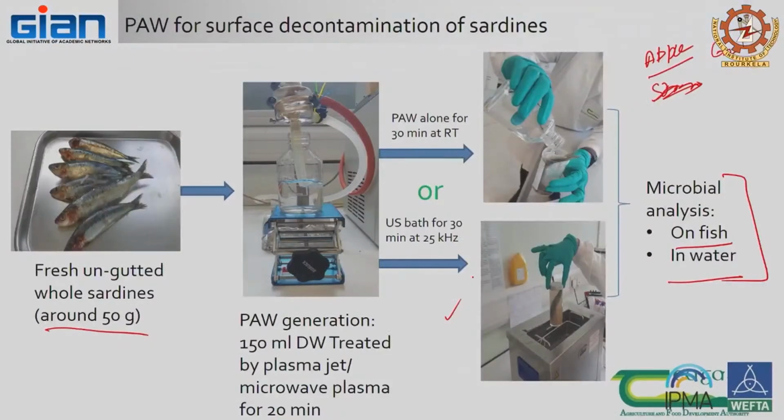Whereas when you use the same thing with ultrasonics, it allows the water to go to the remotest places to do the cleaning effect. Same thing in a vessel. If a vessel has sharp edges, you will see everything deposits at the edge, because that is inaccessible. To make it accessible, use a combination of plasma with ultrasonics.